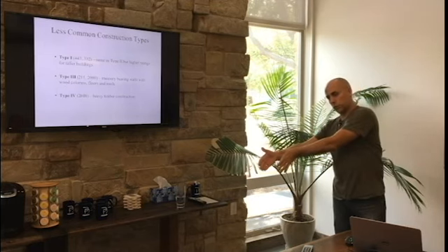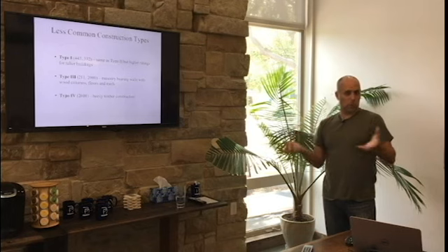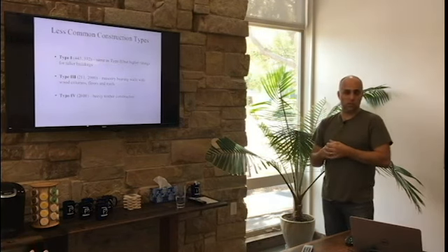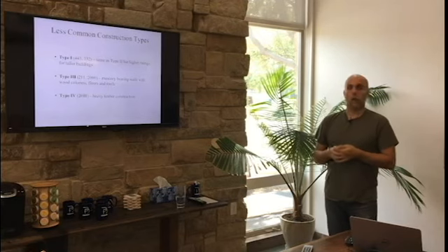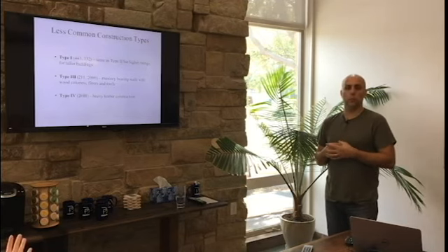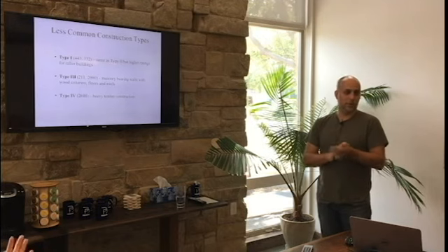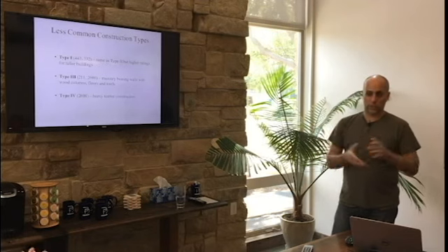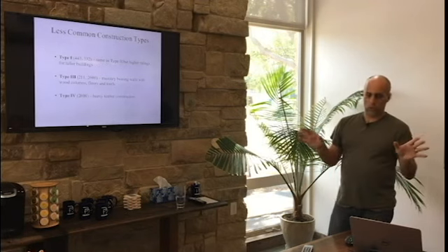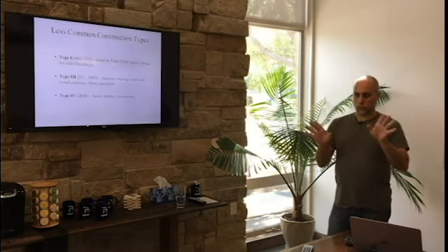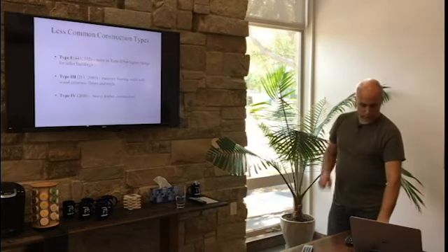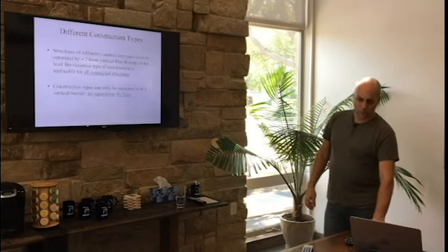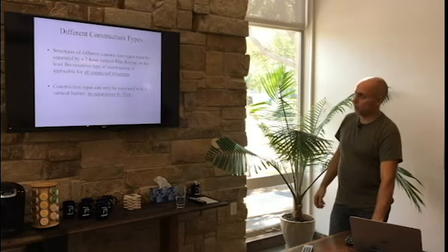That 06 edition of 220 permits FRTW plywood in a type 2 building. So it says you're allowed to use it. So you could do roof sheathing on an all steel building using FRTW plywood, which is really expensive. We as a company are not going to do that, plain and simple. If you're doing a steel building, we're doing a steel deck, because then it's all non-combustible, and then it's just no arguments whatsoever. Under the 2000 edition, you could not do that, and there were a lot of facilities that got in trouble for trying, because they were looking at later editions of the code that were not adopted yet.